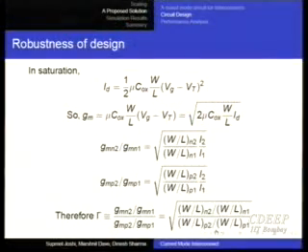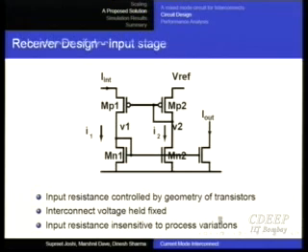Now you can go ahead and make current mode circuits, which will determine the amount of current. So what have I got? This current source sees a zero input impedance. Okay? As a result, when this current fluctuates from 0, 1, 2, 3 delta I, the voltage here doesn't fluctuate at all. In fact, it stays put at the value of Vref. Okay? And that is what the beta multiplier does.